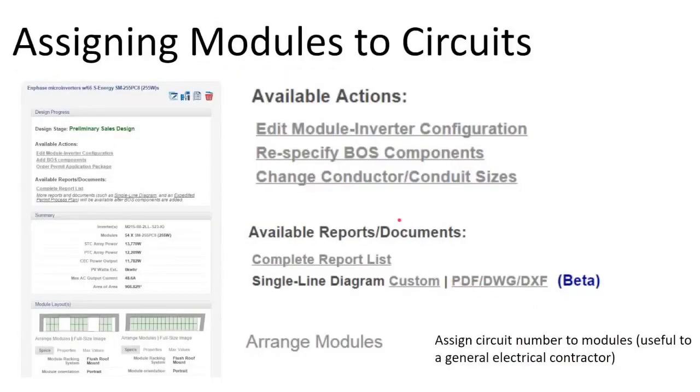But Solar Design Tool has a plethora of final design detail documentation, more than really any other software. It provides the most detailed out of the box one line diagram, which is pretty impressive given that it's on the low end of price, with the caveat that its tools are really geared towards small residential projects, 4 circuits or less in general. Sometimes I'll model larger projects and then stitch them together in CAD afterwards.